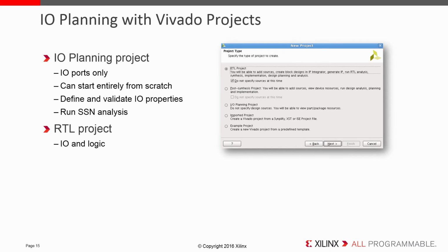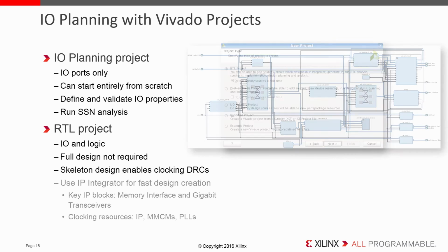An RTL project adds I/O related logic including clock generation circuitry, and note that a full design is not necessary. A skeleton design is sufficient for finding problems with I/O assignments and running clocking design rule checks.